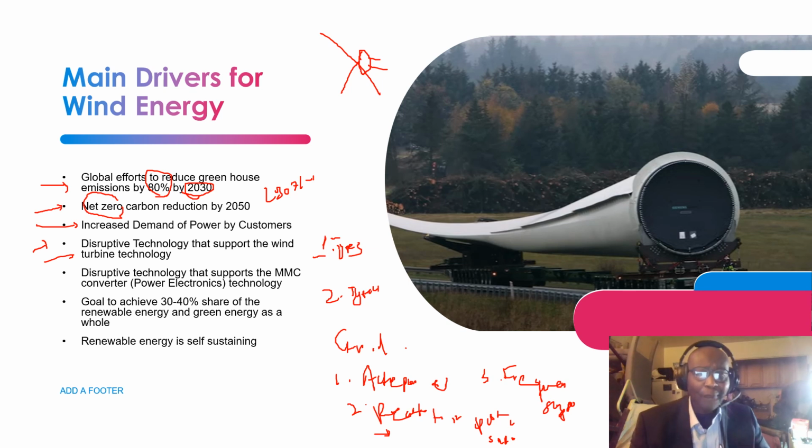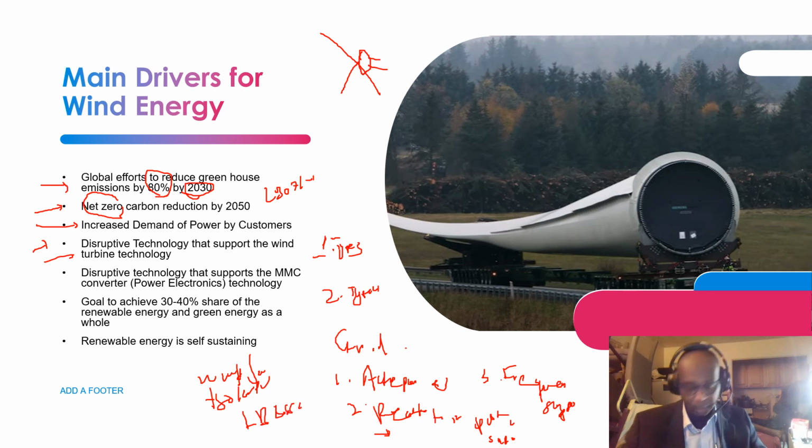Then again, you have the ability to achieve a hybrid wind plant by integrating a wind farm plus a solar PV plus a battery energy storage system, right? What these three power generation sources do is complement each other through an energy management system. So when you have low wind velocity, that is when the solar PV comes into play to provide the required power that you need.